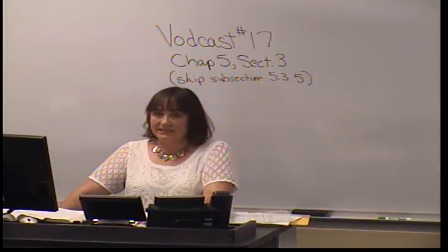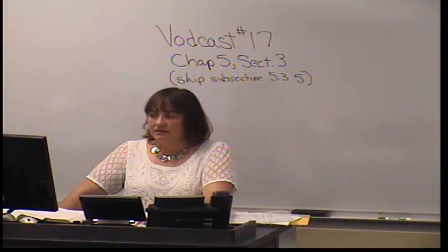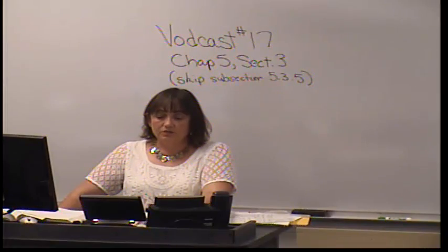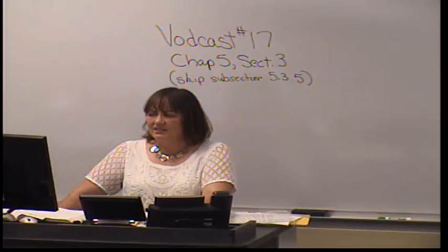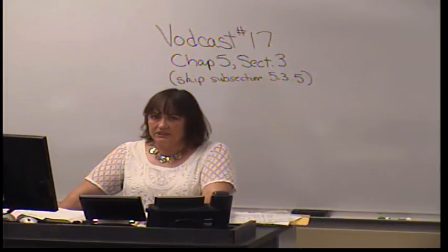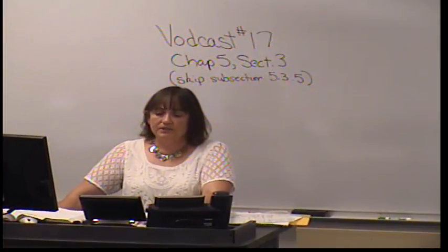Now, a big assumption in this is that we did not have any losses. We were told that the head losses were negligibly small, but in most cases the h sub L term would not be negligible, and we would have to take it into account. I think it's kind of unrealistic, because if you're going through a hose and a hydrant, there are a lot of places to lose head. If I were really designing this, and it called for a 5.5 horsepower pump, I would definitely think 10 would not be too big.